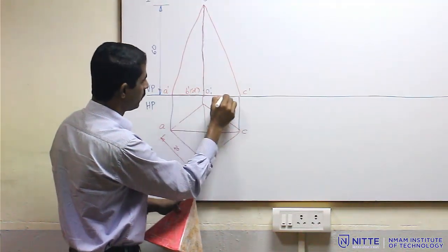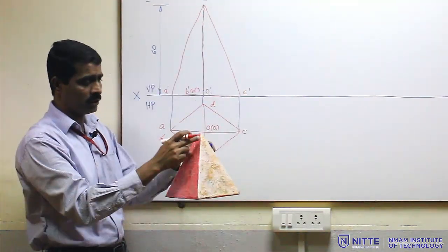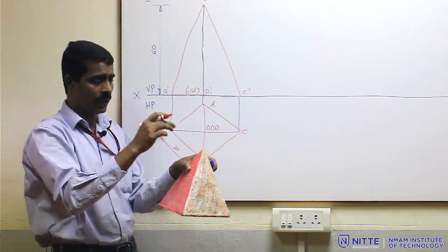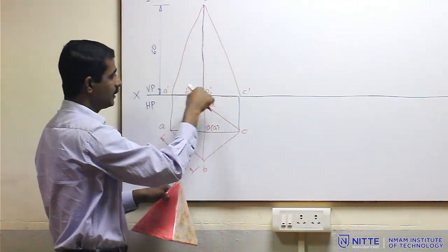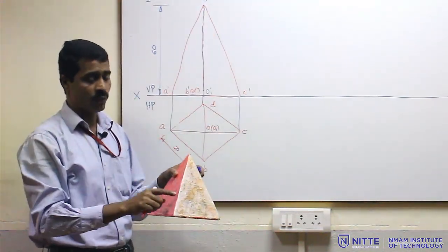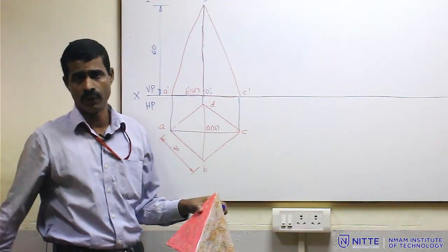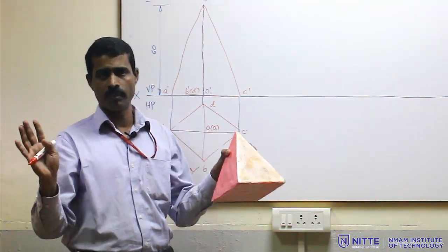So, basically this will become the front view. I cannot represent the axis line here, because the axis line is exactly overlapped by the edges. So, this line is also a thick line. Whichever lines are drawn with red color here, this triangle and this line, all are visible edges, all with the 0.4 mm thickness. So, this is common in all the pyramid or prism problems.